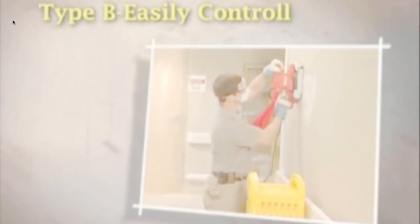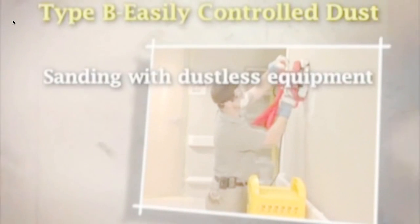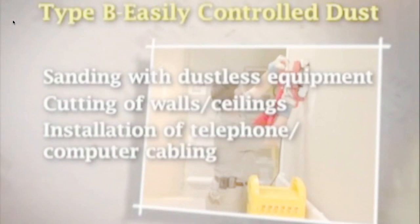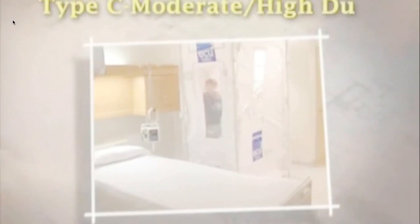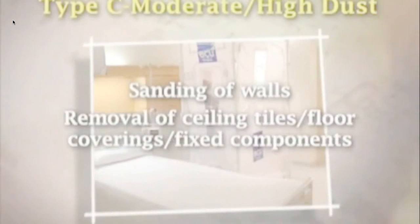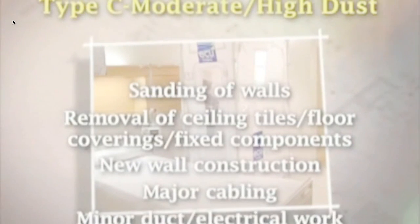Type B or easily controlled dust-generating projects include sanding with dustless equipment, cutting of walls or ceilings, installation of a single telephone and computer cable, and brief access to chase spaces. Type C or moderate high dust generation projects include sanding of walls, removal of multiple ceiling tiles, floor coverings, or fixed building components, new wall construction, major cabling activities, and minor duct and electrical work above ceilings.